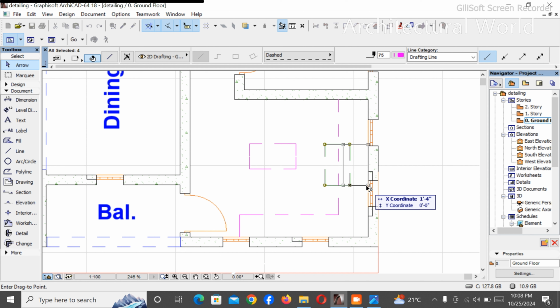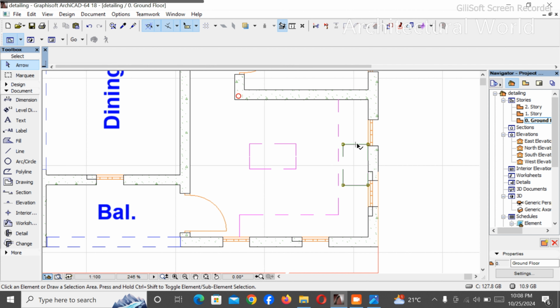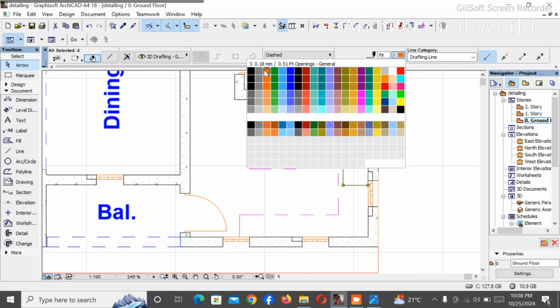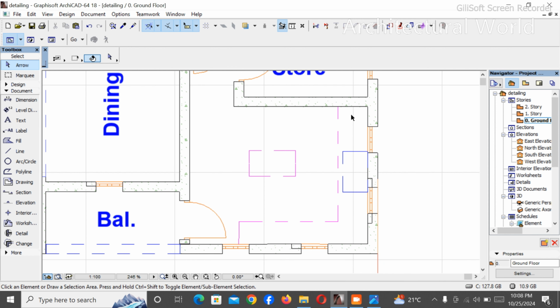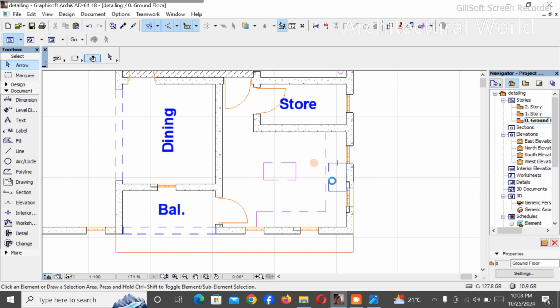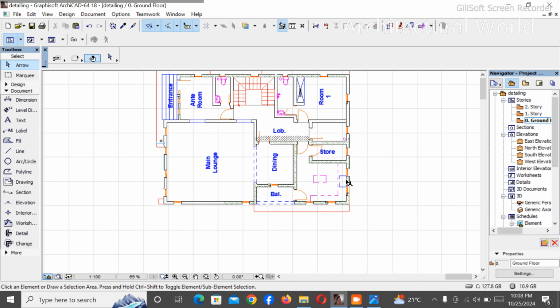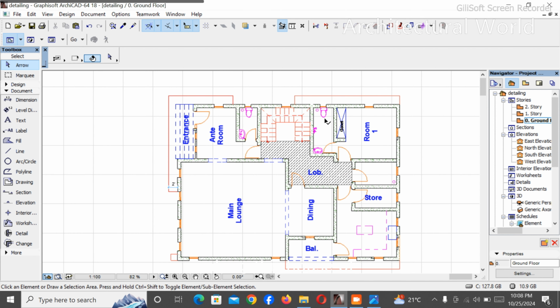Now let's take this as our sink. This is our sink. You can see very well. Let me change the color to blue. This blue here is our sink. So these are for cabinets. The reason I take this blue closer to this part is because I can easily run the waste and water this way. Now let's assume I put the sink here. I have to run through this part, and that is a waste of material and a long distance of slope.